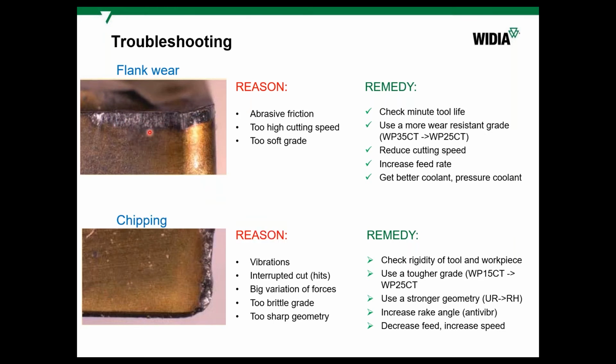On the flank, also on the clearance face, there is a line which is abrasively worn out. It's slightly even, and it is a maximum positive wear we can face with. We need to achieve this wear, but if this wear appears not very soon, usually it's abrasive because of contact with material for sure, because of the abrasive friction.